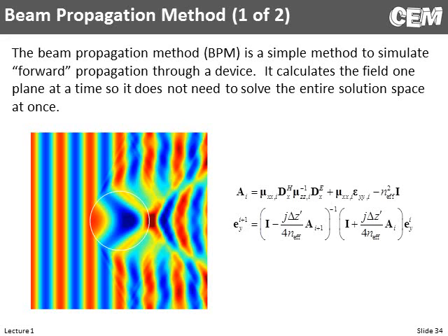So here's a big dielectric blob. The wave hits it. Notice nothing's getting reflected. Clearly that's not physical reality. A lot of things can still be modeled somewhat accurately that way, but you solve it one slice at a time. So you're not solving this all simultaneously, you're going one slice at a time. So numerically it's a bit more efficient. But since you're doing that, it doesn't account for backward energy.